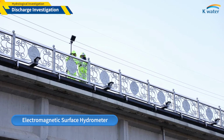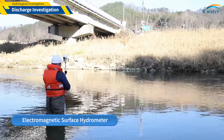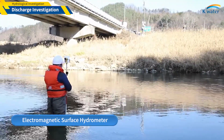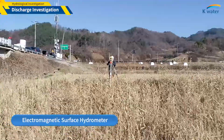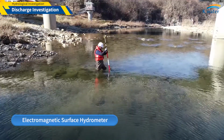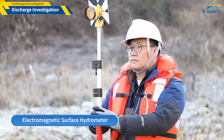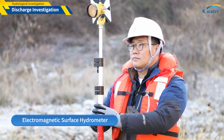The hydrometer should be installed facing the upstream of the river and repeat measurements while moving to various places, considering the width of the river. The electromagnetic surface hydrometer cannot measure the depth of water, so streams must be measured before flood season. In conclusion, the discharge can be calculated using river survey data, the distance by measurement location, and measured velocity.